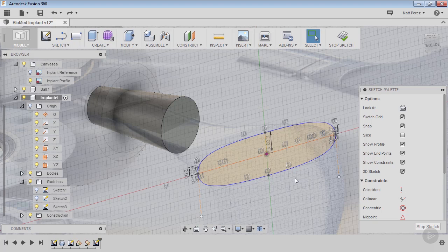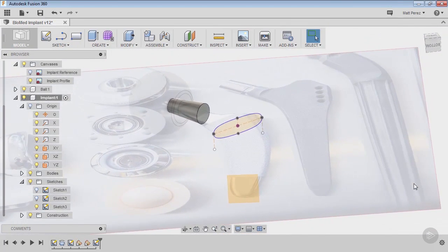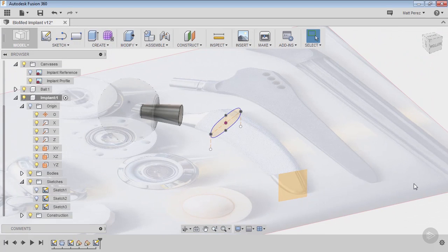I like to let the splines sort of do their thing where I don't have to define them. I know that I need this to be 5 millimeters tall at this point. I know that I need it to have tangency going across here. And other than that, I really don't have a very stringent list of specs in terms of this profile here. I just know that I need it to be nice and smooth and organic. So for this design, for this instance, we're going to leave it underdefined, which in general, again, I avoid. But in this case, this is actually what I want to do. I want to leave it underdefined to make sure that the shape is not pushed or pulled or stressed into something that it shouldn't be.